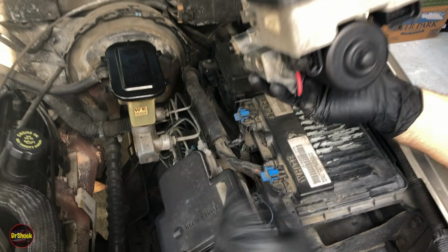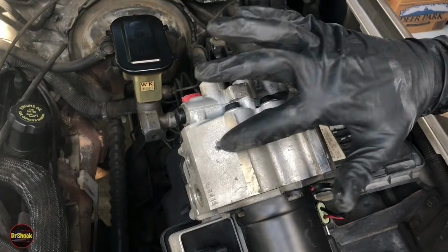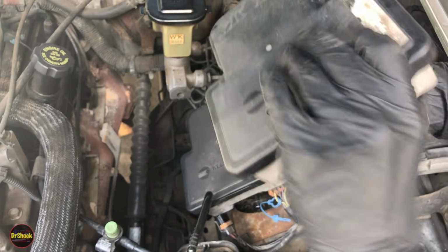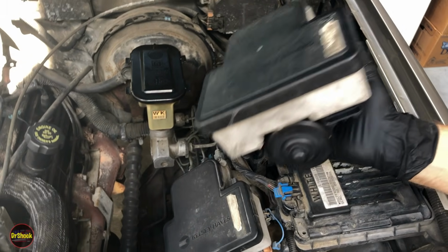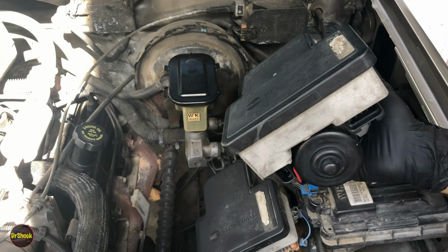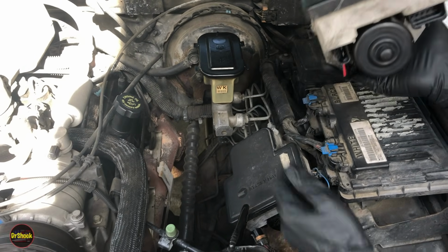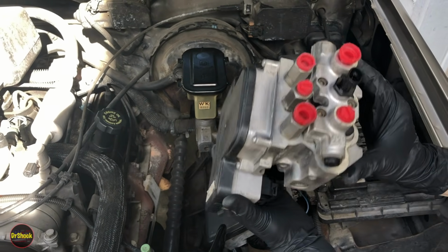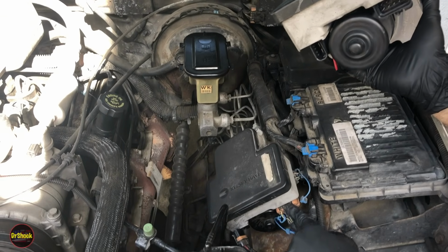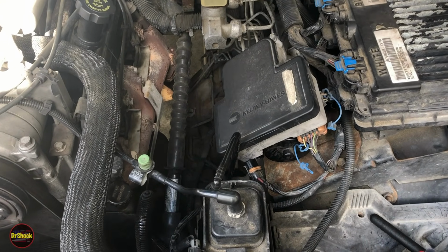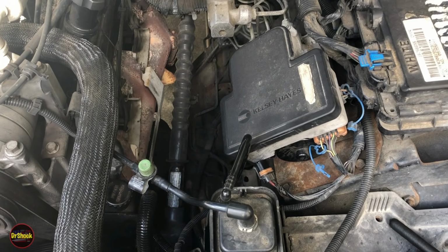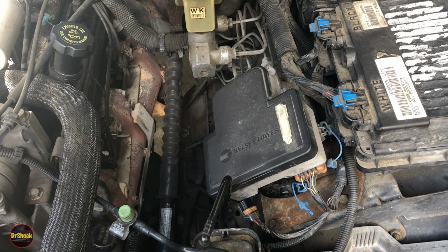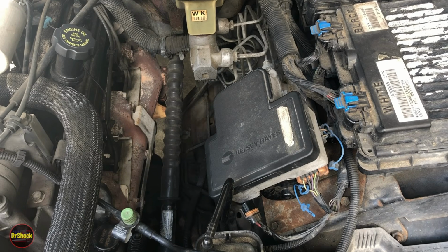So this is the guy we're going to put on there, and we're going to have to get him off in order to mount him onto that bracket at the bottom. So the way we're going to take this out is this unit on the bracket intact, and we're just going to lift the whole thing out. We're going to take these two 13s off down here. We're going to release the fittings on the brake lines. They're on these five on this side, and then the other two 13s, and we're going to take the whole thing out. And then we should have a better shot at getting this really wedged in, baked on connector. It's been sitting here for two and a half decades. It's not really interested in being disturbed. So let's go ahead and get going with that.